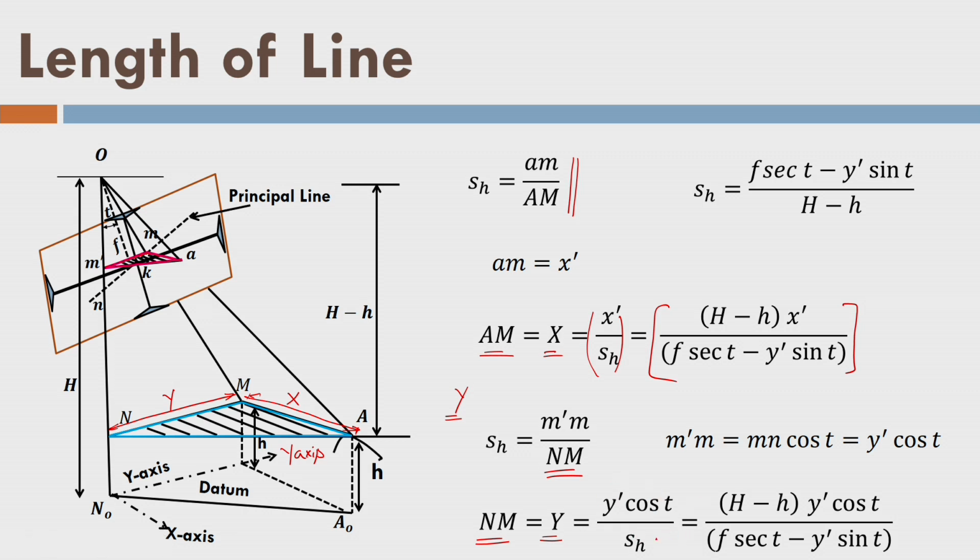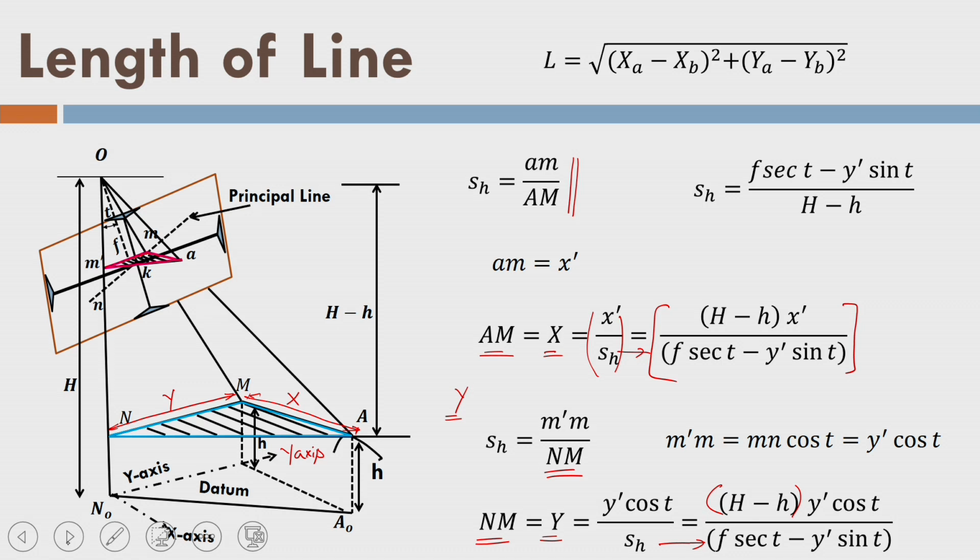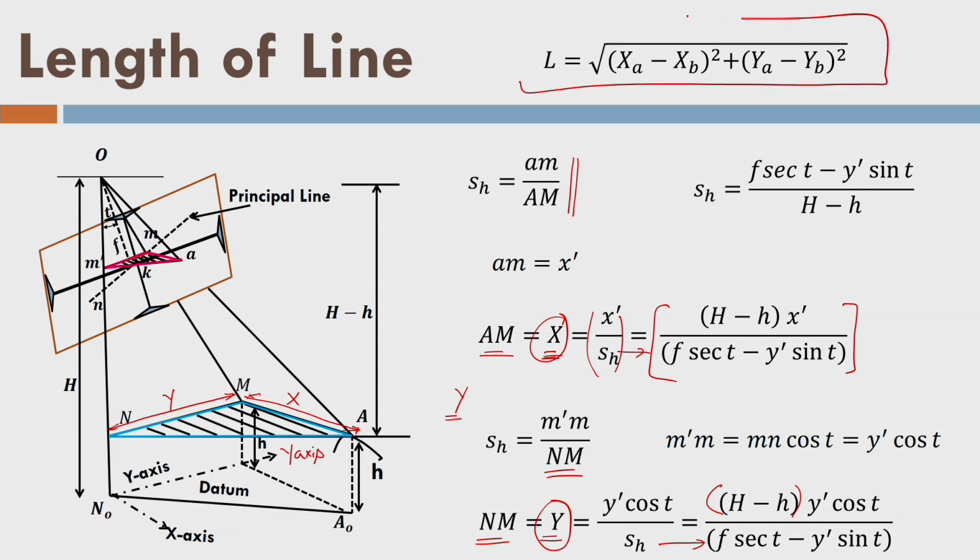Then I put in the values of sh and h minus, so I am putting in the value of scale only, because of the inversion it comes this way. This is my scale sh, I am putting it here also. Now, I can say what the distance is between 2 points. Let us say you measure x for one point, and y also for point A. Similarly, you measure for point B, and then you can find the length on the ground surface, which is equal to this distance. That is the idea here.